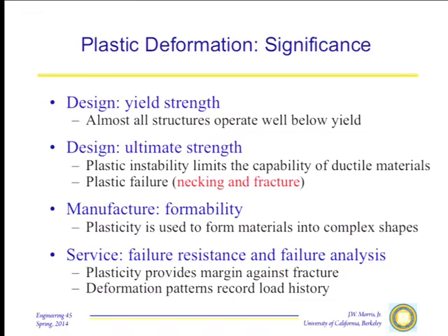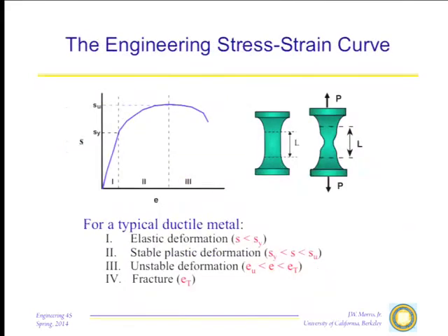Finally, in service, failure resistance and failure analysis. The plastic deformation of a material is really what gives you your margin of safety between the elastic deformation you design to and the ultimate failure. And in fact, we'll see that when we get to fracture, but just from the stress-strain curve.